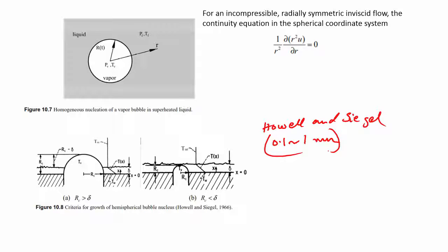If you look at it now, there are two scenarios that are possible. When the cavity size, half of the cavity size, essentially RC, is so large that a part of this bubble actually sticks out above the thermal boundary layer, which is given here, that is the thermal boundary layer thickness. Got it? So, a part of the bubble basically sticks out. And in the second case, most of the bubble is actually encompassed within this thermal boundary layer.